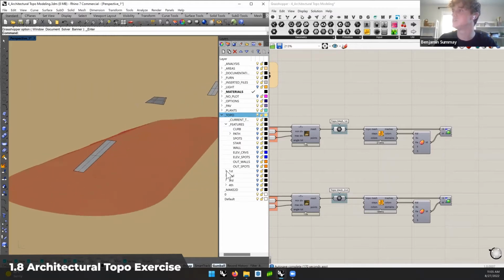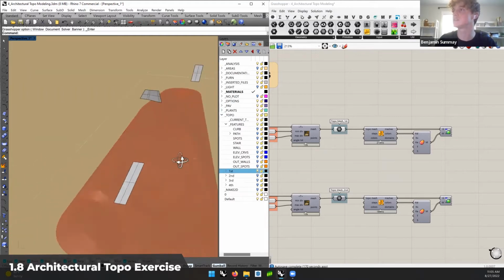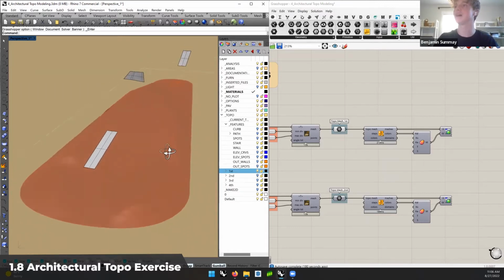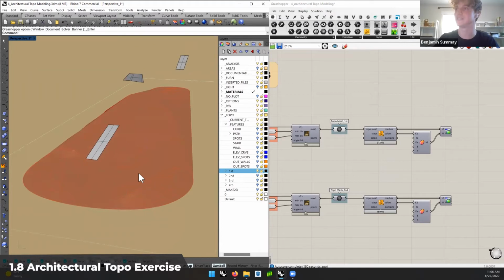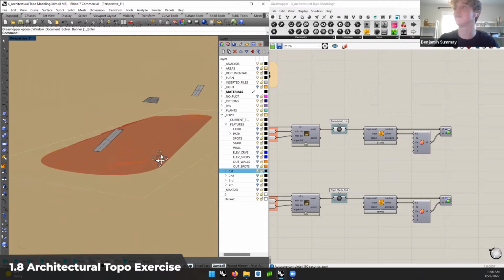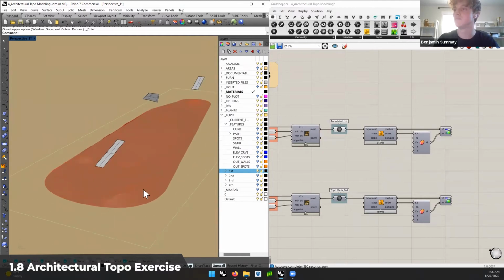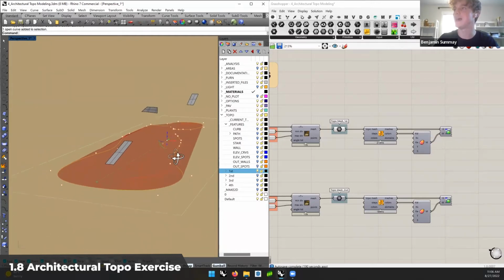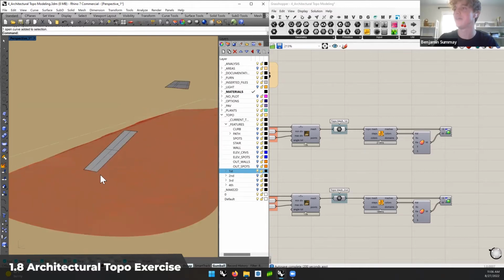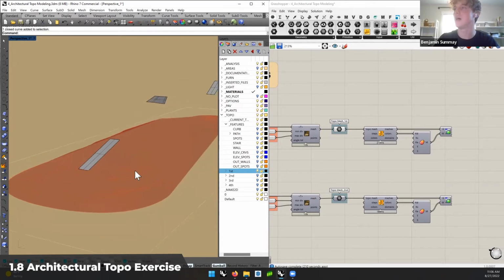But the geometry that I'm using to construct it is focused on the edges of where I want the floor to actually be represented. So I have these break lines, a series of break lines representing the different parts of the topography that I'm constructing and forming here. It's not very much geometry. It's just some break lines that represent contours to create our mounds, a bounding edge that represents the raising and lowering of the overall floor on the outside edge, and then a few lines here that help meet the staircase at the bottom for this surface.